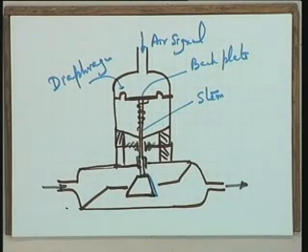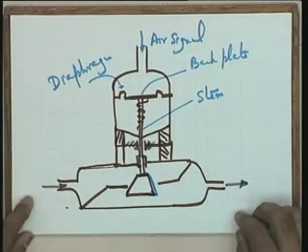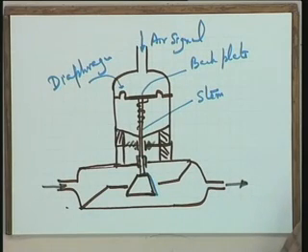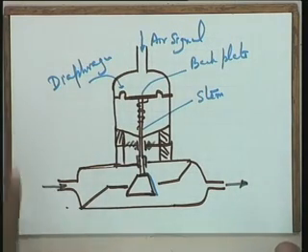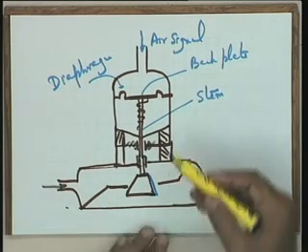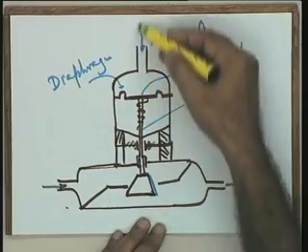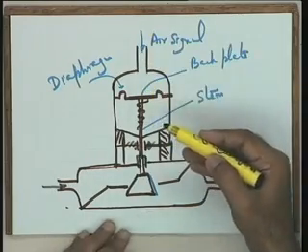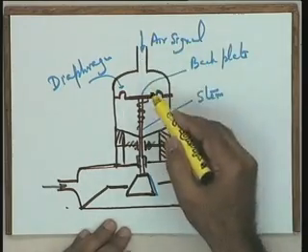In this particular case you are simply controlling the opening of this particular valve. This is the control valve. This complete unit as a full assembly is commercially available, and it is so extensively used in the process control applications that your attention is very much needed over here, though we will make many approximations to model this particular device. So, in this case you just see the air pressure is the manipulated variable, this is the air signal coming.